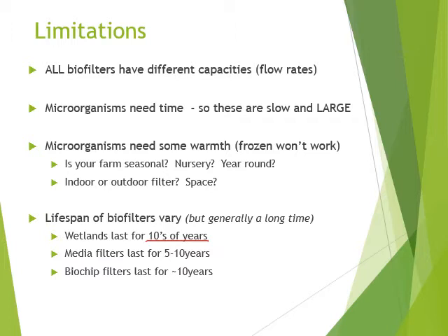Media filters, depending on the type of media, can last anywhere from 5 to 10 years, and then it starts to break down. Biochip filters, which rely on the media being consumed, like wood chips, are up to 10 years, which is not bad. That's pretty long. It's astonishing how long they last. But again, depending on how much biological load and how much activity and all those other things, the temperature of your climate, they all impact how long it lasts.